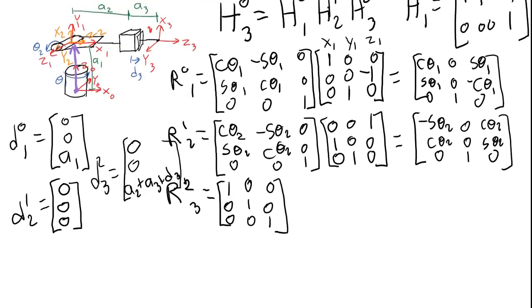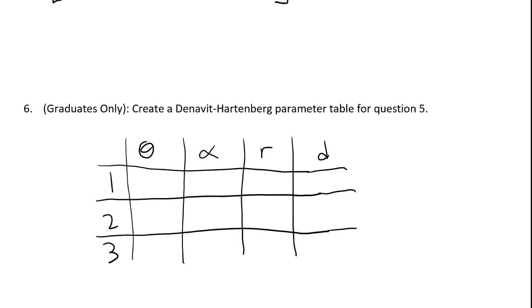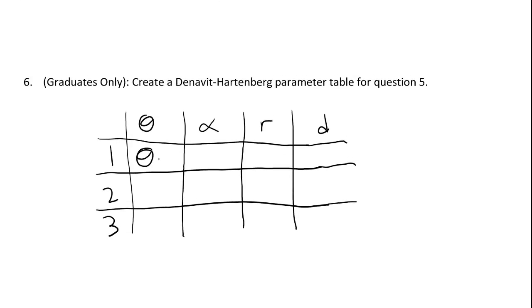Theta is the rotation around the z-axis. And the z-axis that we're looking at is the zn-1 axis. So for the first row, we're trying to see, how do I have to rotate frame 0 around the axis z0 in order to get the two x-axes to match, and also in order to account for the joint variable? Well, x1 and x0 already match, so I don't need any additional rotation beyond the joint variable in order to get those two axes to match. So theta in the first row is just theta 1.